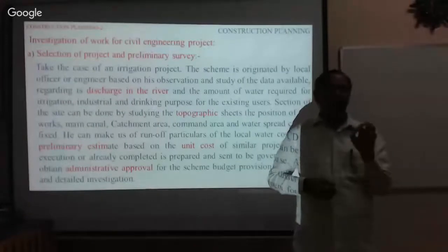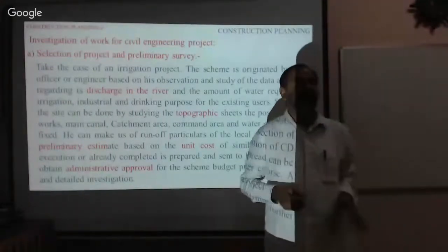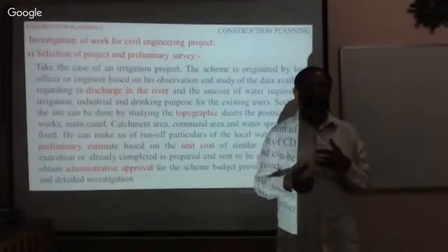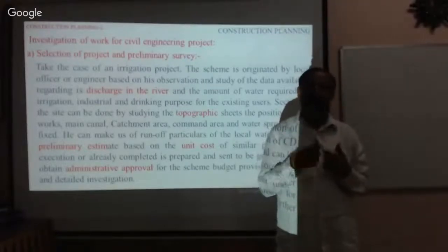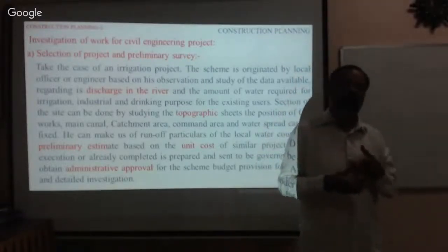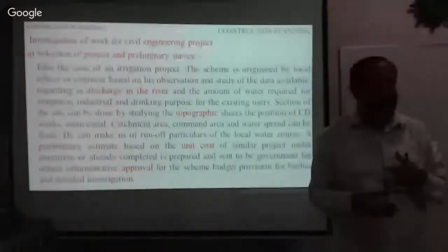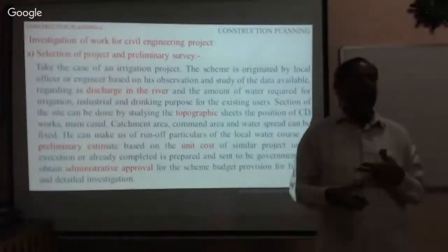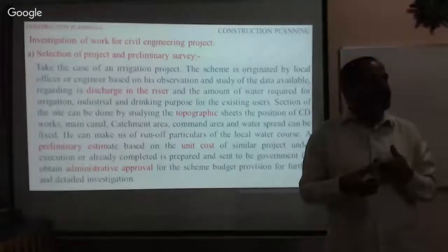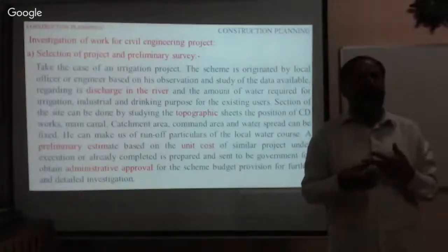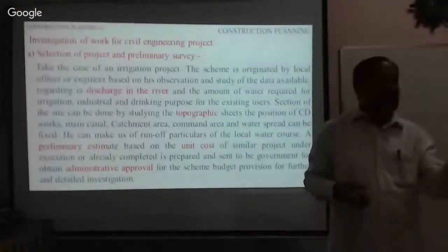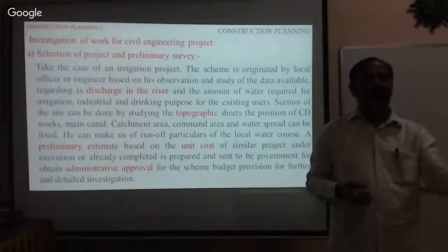Now, suppose you are constructing a dam for irrigation, drinking, and industrial purposes. Let us be very careful. First go to the site, conduct the preliminary survey, and then the detailed survey. In the detailed survey, you have to collect the ground data. What is the amount of rainfall?